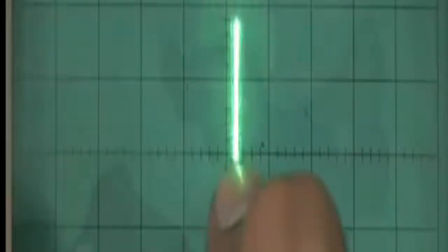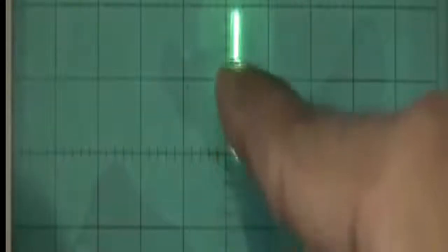Now, this dark black line, which has subdivisions, is your reference line. Using this y-position knob you can move this line and bring it over here so that you can properly count the number of divisions. Now it is here. From here, I count: till here it is 1, from here it is 1.2, 1.4, 1.6, 1.8, it's almost touching 2 but not 2. So let us take it as 1.9. I release the XY.